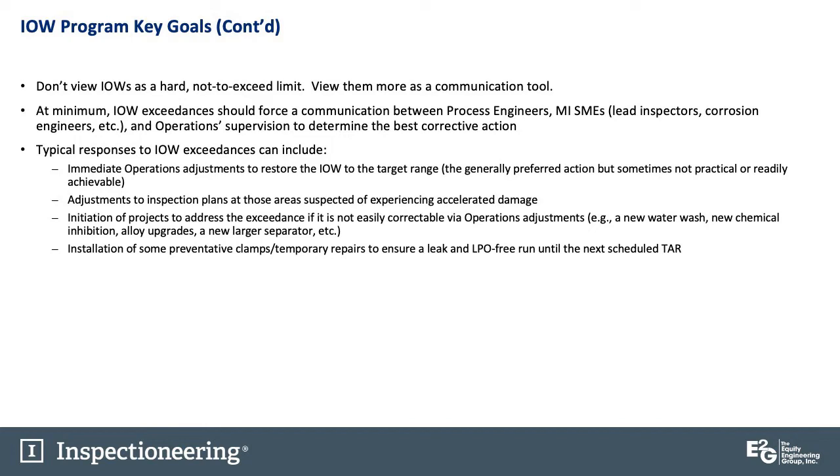Another response could include initiation of projects to address the exceedance if it's not easily correctable via operations adjustments. So maybe we need a new water wash, some new chemical inhibition, some alloy upgrades, a new larger separator, all those types of things.